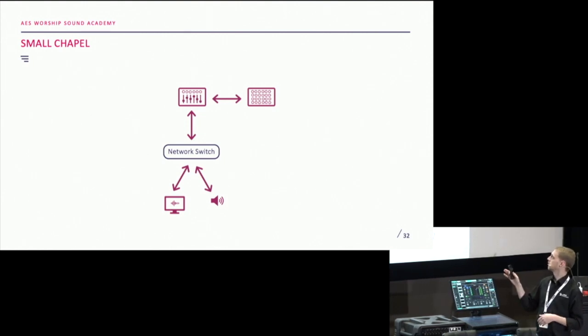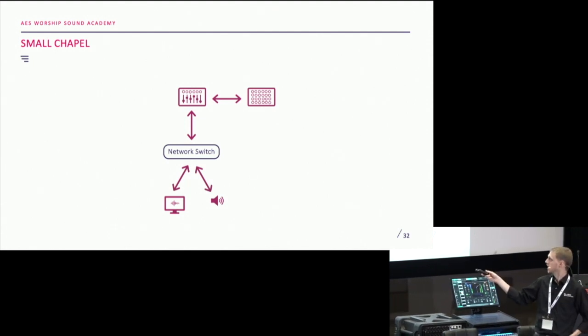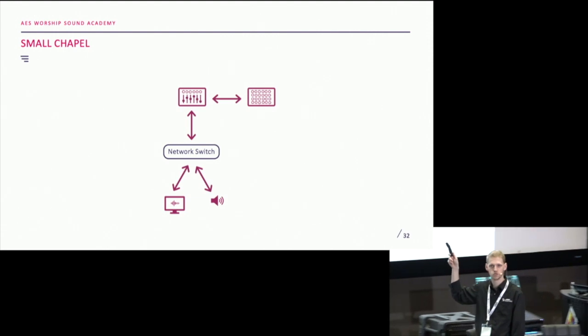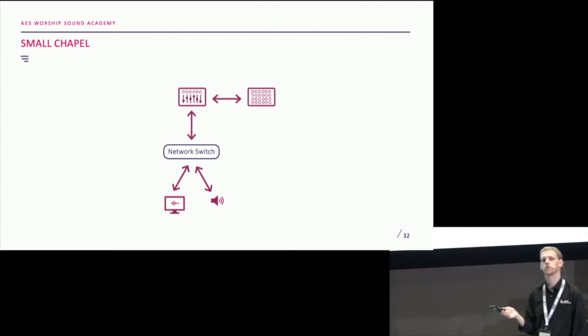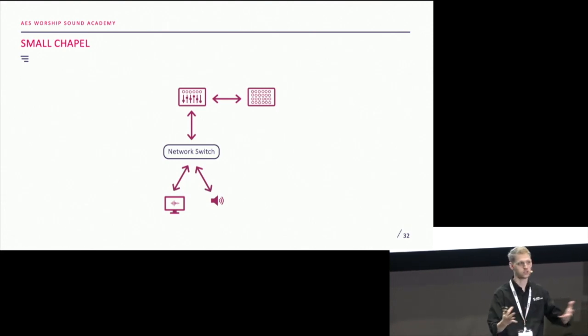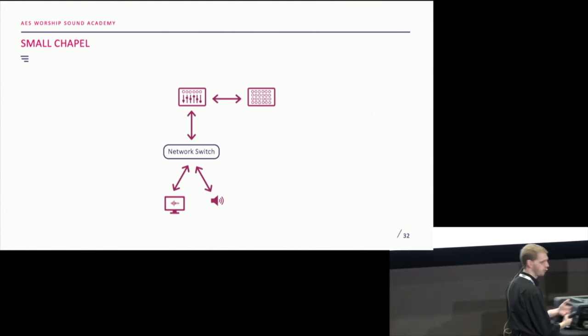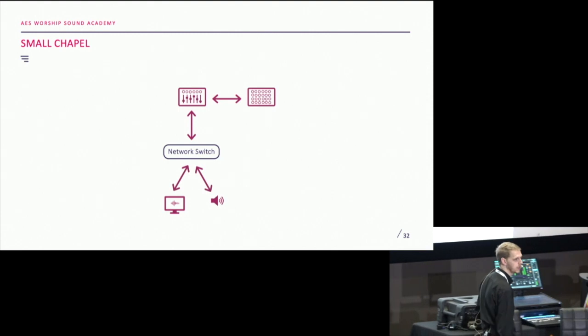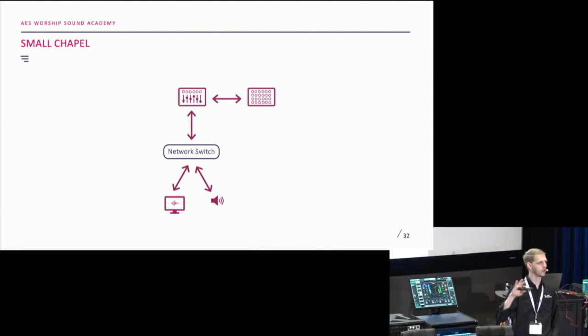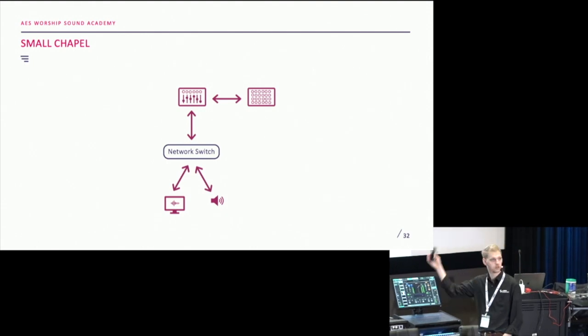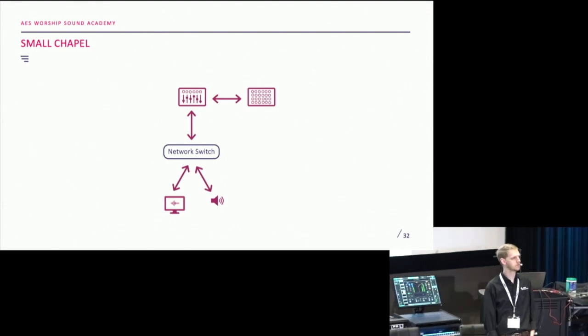So now we have flexibility. We're actually running kind of 2 systems. The amplifiers and potentially the multi-track computer don't really know anything about the stage box because it's on layer 1, going over AES 50. So it's up to the console to tell them, hey, I'm going to provide these channels to you for multi-tracking. I'm going to provide these channels to you to send out to the PA. So now we've kind of got a mixed system between layer 1 and layer 2 solutions. But still all valid audio over IP ways to go.